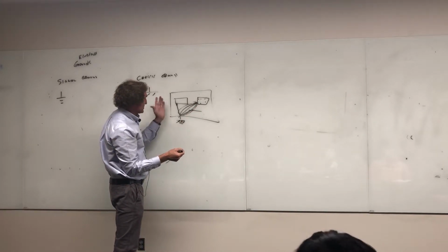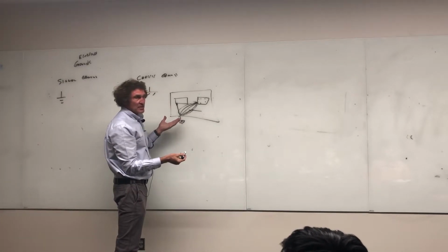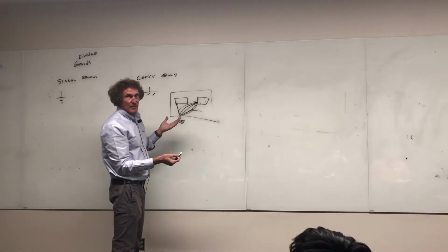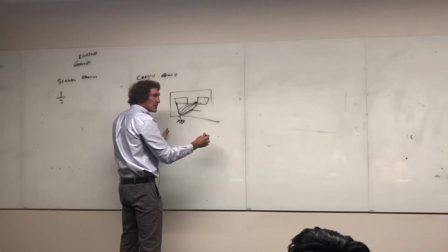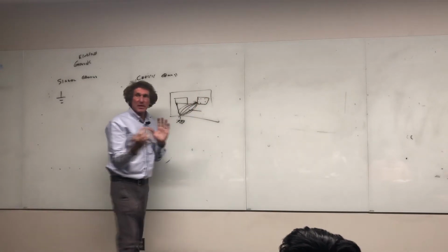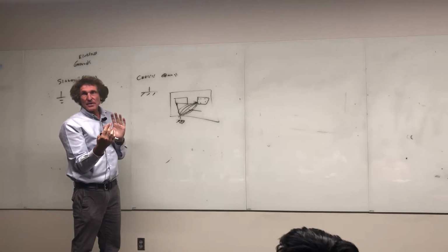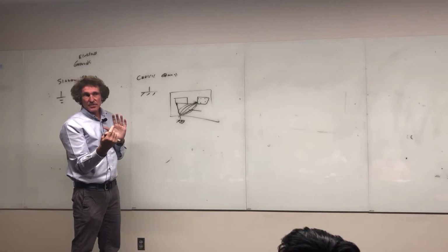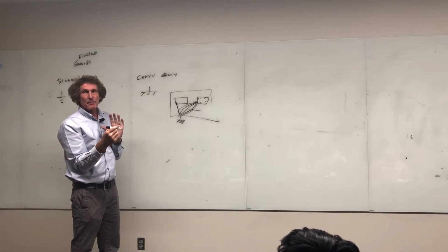Now, so this is a chassis ground. I'm going to tell you other warnings about this. In cabinets especially, where you get a bunch of different chassis stuck in a metal box, you can get all sorts of weird effects for the high frequencies. And you can get parasitic capacitances causing problems. We'll get into ground loops.